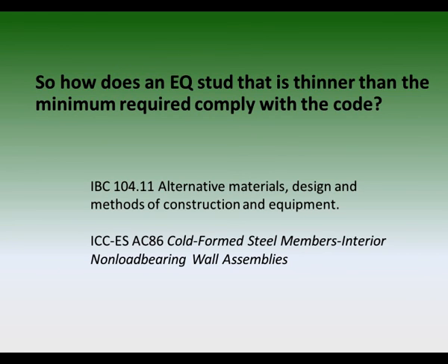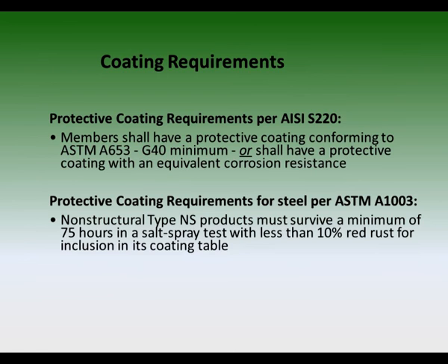But what about the coating requirements? AISI S220 requires a minimum G40 or equivalent corrosion protection. The key with EQ studs is the phrase equivalent corrosion resistance. As we covered a few minutes ago, ASTM A1003 is referenced in AISI S220, and that's where the equivalent requirements reside.